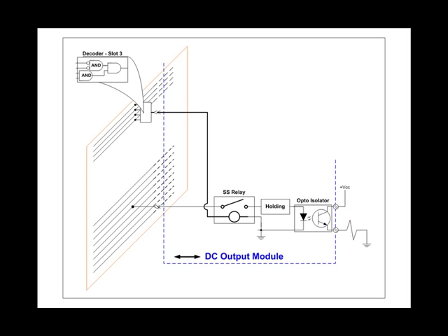After the states are put on the backplane, the processor sends a slot number down the control bus, in this case a binary 3, 0011. This activates slot 3. The activated card connects the 16 states on the backplane to the output circuitry via the solid-state relays in the holding circuit. When the processor deactivates this slot, we can't have the output turning off again, so we need a device that will hold the last state sent by the processor. That's what the holding device is.